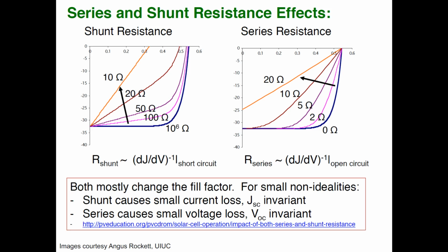You're correct. So if you see from these plots here, this typically means the same thing. It's actually difficult to make you understand without the videos, but I'll try my best. The more shunt resistance you have, the more you approach the curve where I showed that you can have the maximum power, and that can again happen with as little series resistance as you can have. So for these two combined effects, you need to find the trade-off across your solar cell.